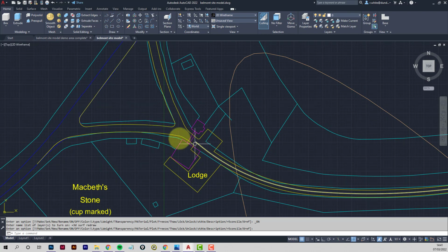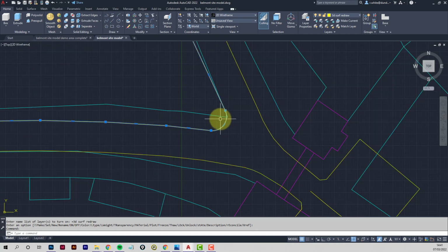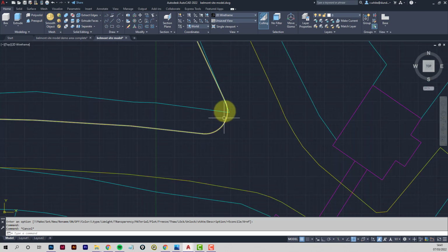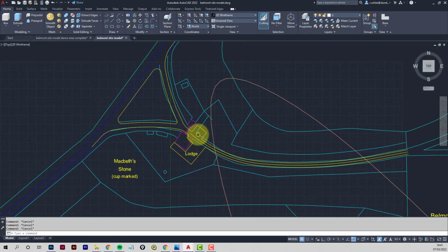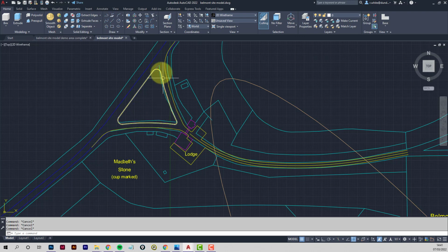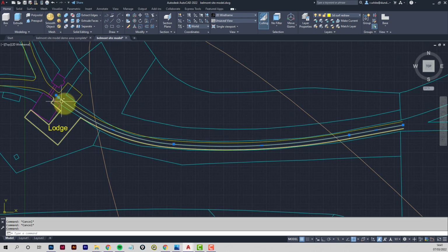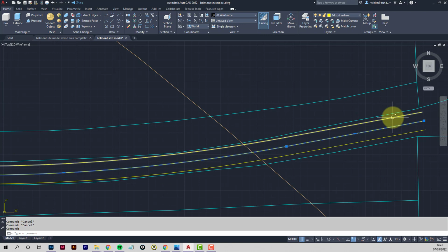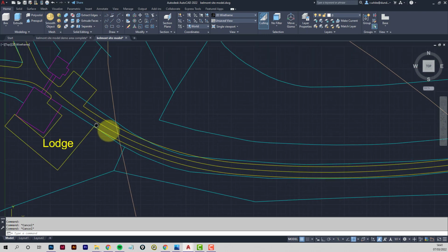So using lines wherever possible, because that does make the modelling a bit easier if there are more lines. But where we've got two roads meeting here, this Y junction, I have used a radius so we get something that looks a bit more appealing. Okay, so I've done that for the three corners of the triangle, and then set up a polyline down the middle of the driveway so that it can be offset either side to get a nice parallel path right the way into the site.